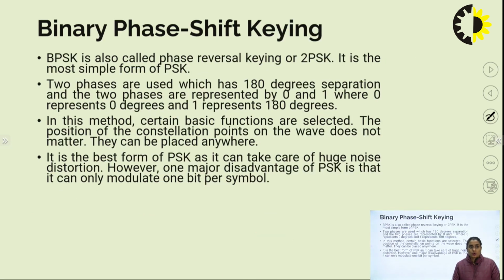BPSK is also called phase reversal keying or 2PSK. It is the simplest form of PSK. Here 2 phases are used, which have 180 degrees separation, and these 2 phases are represented by either bit 0 or bit 1, where bit 0 represents 0 degrees phase shift and bit 1 represents 180-degree phase shift, or vice versa could be the case, right?